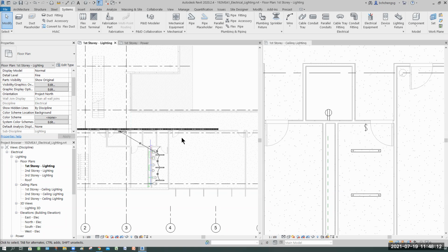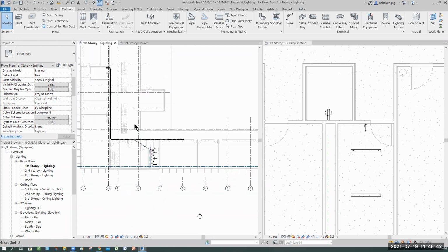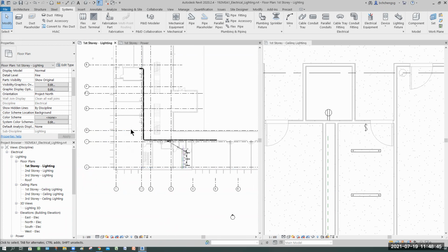So the sub panel can be smaller now. Because the consumption here is normally not high, they normally share. Consumption not high, so I don't think they'll often trip. So at least you maintain it here. This one can accommodate a few areas: your lounge, your toilet, heater. I think these can be together. Some other rooms, maybe the instruction room, can be on its own or here. It depends on how the electrician or engineer plans this.